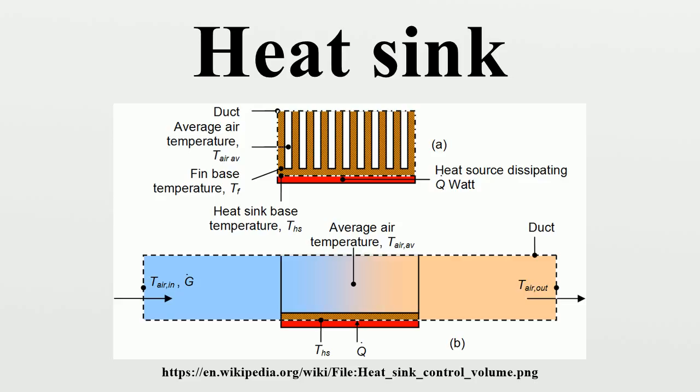Optimization. The shape of fins must be optimized to maximize heat transfer density and to minimize the pressure drop in the coolant fluid across the heat sink, where the space and the materials used for the fin surfaces are constraints. Many shapes exist in the literature, ranging from elliptical and cylindrical shapes, conical shapes, to more sharpened surfaces such as rhombus and square sections.